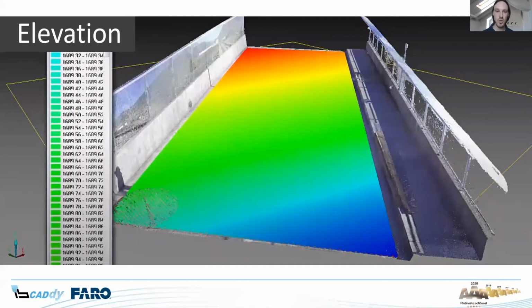Another application are storehouses. If you have a storage and you need a very flat floor, because sometimes you drive over there with your machines, with your lifters, and they're sometimes lifting up tons of material up to 5 or 10 meters. And if there's just one small deviation in the floor, it can, of course, make the entire lift very unstable, which is dangerous. So our scanners are regularly used in storage houses to control if the floor is still flat, or if you are ordering those warehouses for someone to build for you, you can check if they are within the specifications you ordered.